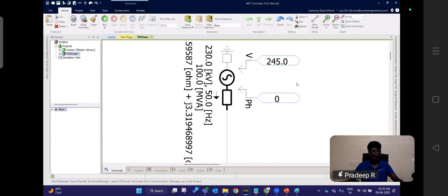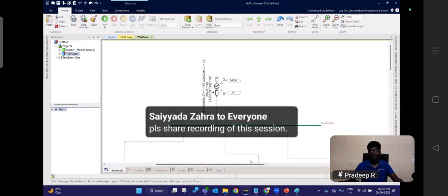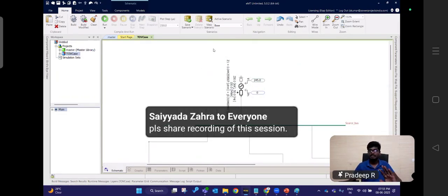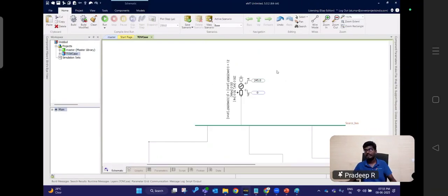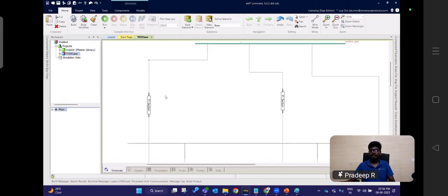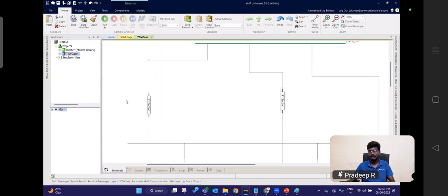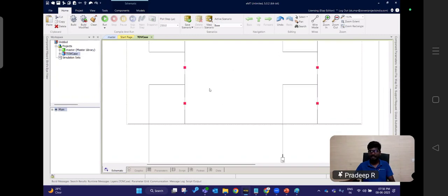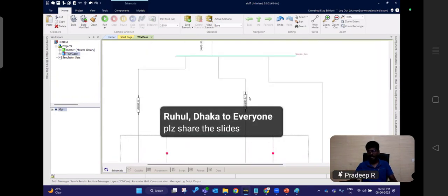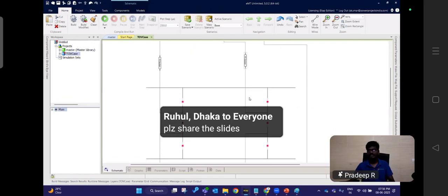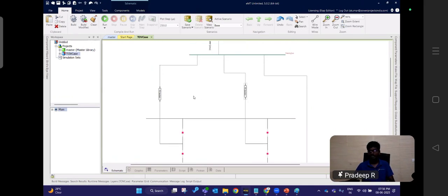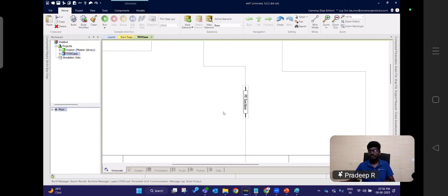Starting from the source, all the substations, everything, will be modeled as a source here. In our PSCAD, we will be modeling the entire substation, remote substation, everything, like the grid here, the power grid, that is the source. Following that, there are two cable feeders, CS1 and CS2. Two cable feeders are connecting with my GIS. So this is my GIS. For each study, there is a restriction on how to model each element. So this is the simple model, which is known as bisection.